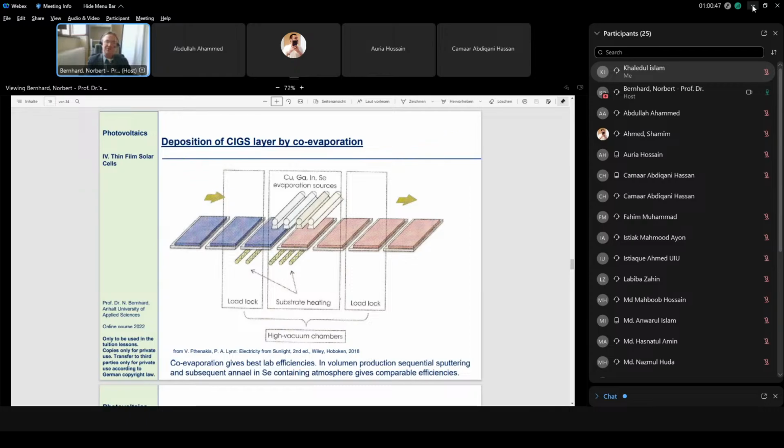And then we have flakes and balls of titanium oxide, which is also a rather high bandgap material. On these titanium oxide spheres there sit the dye molecules. That means the dye molecules are the trigger for the light to electricity conversion. And this is why this is called a dye-sensitized solar cell.